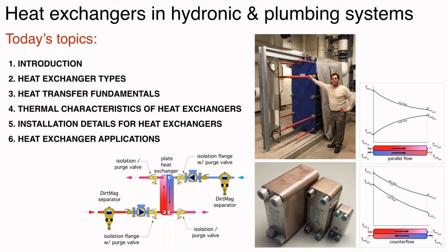It's important to understand these fundamentals because as you apply a heat exchanger, differences in things like temperatures and flow rates, as well as the physical configuration of the heat exchanger, can and will influence its performance. We want these devices to be long lasting. We want them to remain close to, if not at, their original specifications. So keeping debris out of a heat exchanger, for example, is an important installation detail. And we're going to wrap up today's session looking at some applications of heat exchangers.